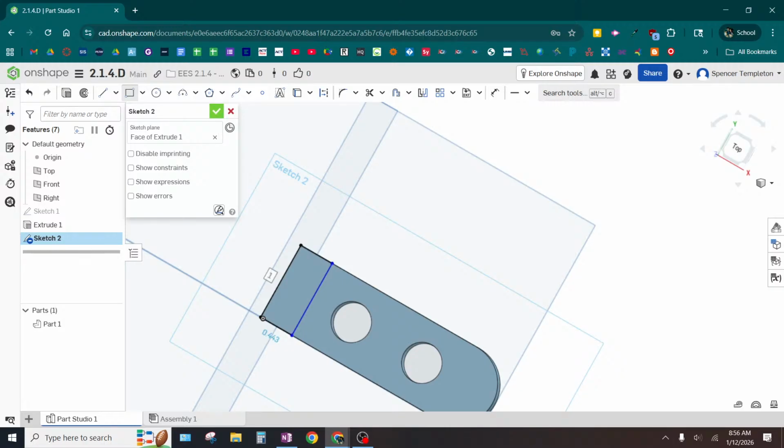I'm using the horizontal constraint to determine their location, right? Think of it this way, like in carpentry. Imagine that I was going to place something every foot along the wall. If I measure from the wall to the first one, one foot, and then measure one foot from the first one to the second one, every time I do that, I'm compounding error. If I'm off by 1/8 of an inch on the first one, the second one now has a propensity to be off by 1/8 of an inch, even if I make that measurement perfectly. The smart choice would be to measure to the wall every single time. And that's what I'm reinforcing here.